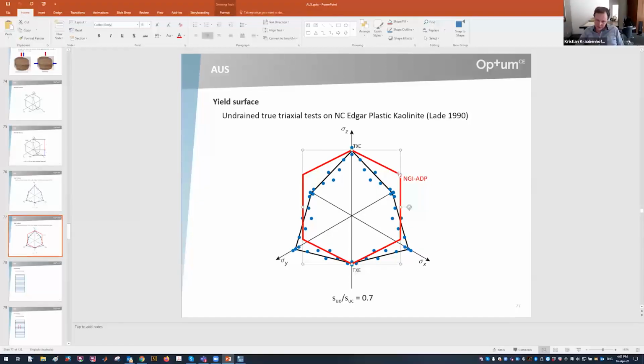the basic assumption behind this model, that the yield surface is a Tresca hexagon, is wrong. It's not a Tresca hexagon. It's a Coulomb type cross section that is actually at play here. So this base assumption of a Tresca hexagon is wrong, and then in order to correct it in the best possible way, anisotropy is introduced, even though the material may well be completely isotropic.